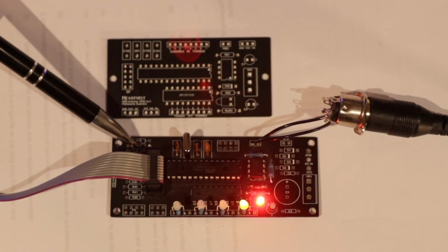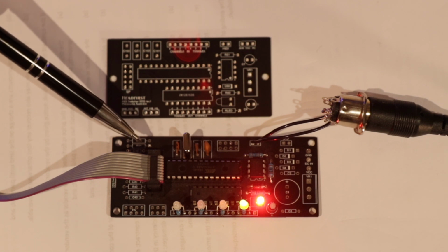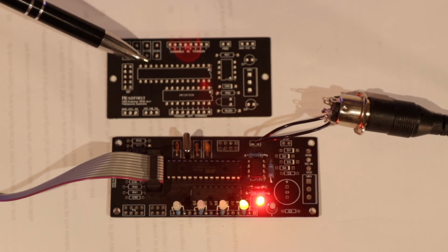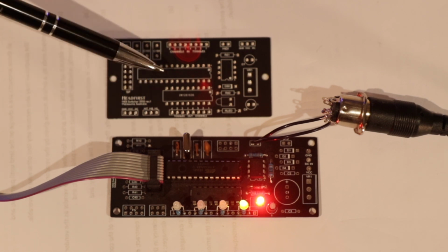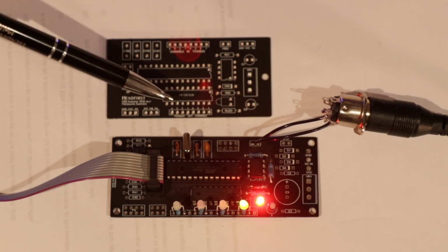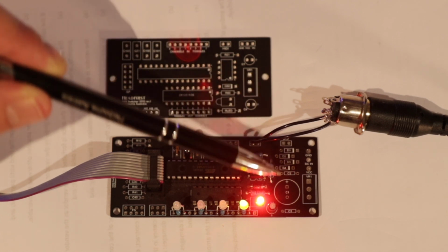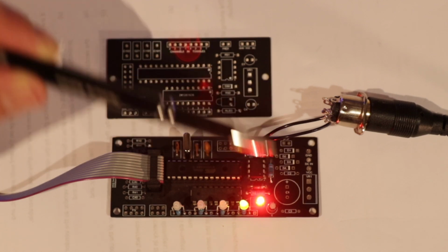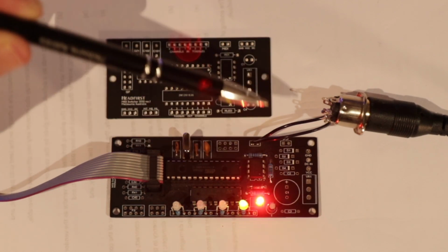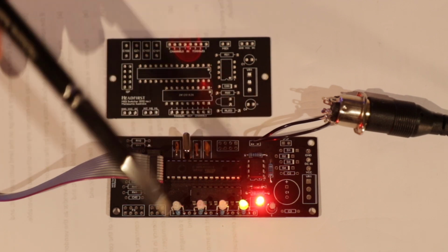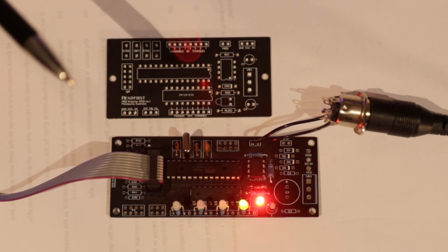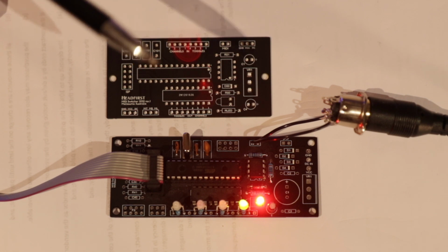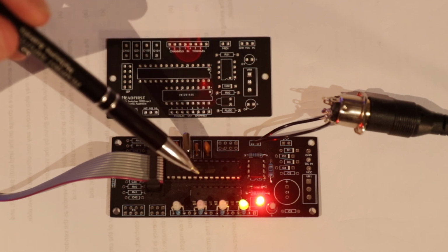This is my first generation MIDI PCB. This is the one that's on sale in the store. You can see it's substantially smaller. The key difference really is that this first generation one had rectification diodes and quite a large filter cap over on this side of the board. So that would be in the event that you needed to create a DC supply for the chip.